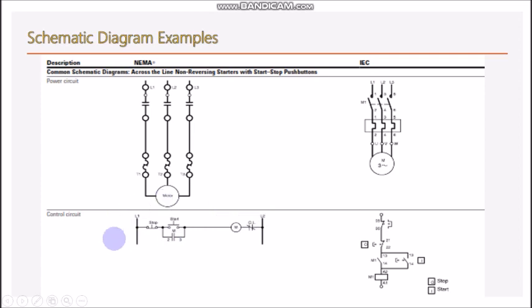This circuit is very simple for start stop motor and very easy to understand. Now for troubleshooting, if the motor is not running and the power is okay, the contactor is okay, and thermal overload is okay, maybe it's the control circuit, maybe the control circuit does not have power, so we need to check the power for the control circuit. Maybe the stop push button has a problem, and it is not connected and not closed, so we need to check the stop push button. Maybe the overload relay is open, so we need to check the points or the terminals of the overload relay.